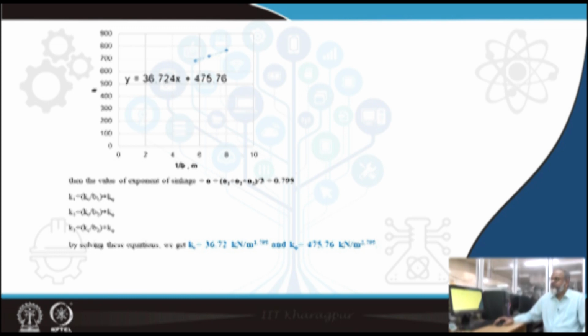Now these are the values for a sandy clay loam soil, where the moisture content is around 10% dry basis. The plate sinkage test, as I said in the beginning, indirectly gives you the response of the terrain. Terrain means the soil, how it is behaving when it is loaded with a tire. So these parameters are required, and this is one of the techniques used for measuring this response of the terrain.